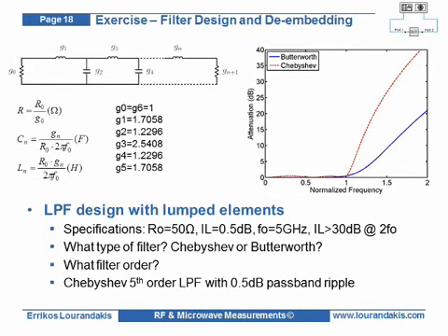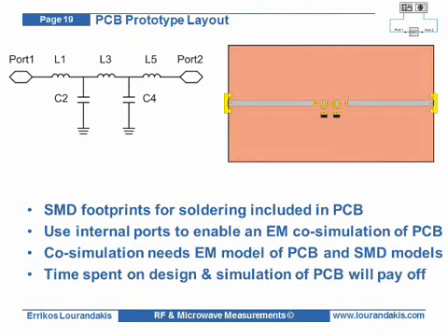We decide to use a fifth-order Chebyshev filter that fulfills the mentioned specifications. Calculating the filter components, namely capacitors and inductors, is now an easy task by using well-known expressions from the microwave filter textbooks. Once we have chosen the substrate material and the dimensions of the transmission lines for achieving the desired characteristic impedance, we can proceed with a layout for the actual low-pass filter.